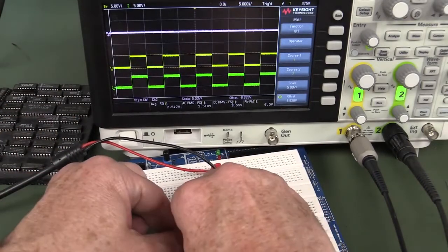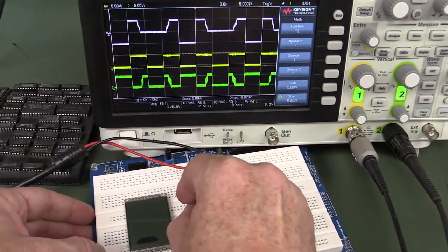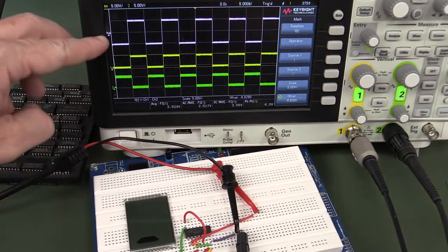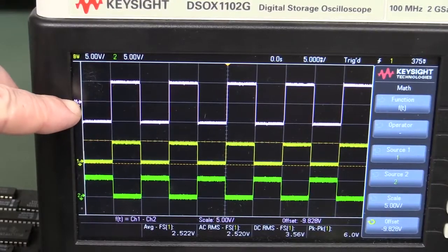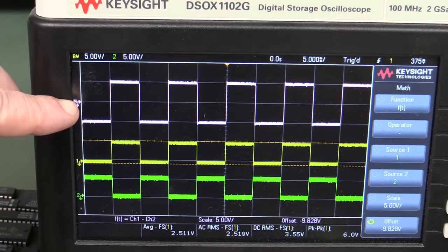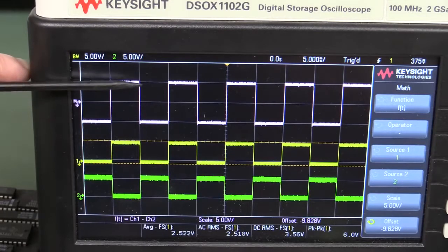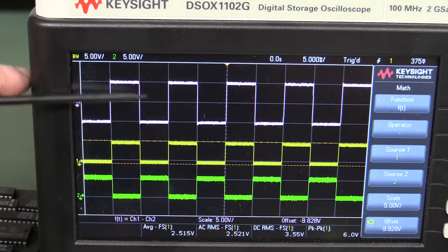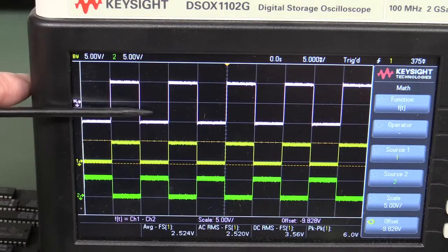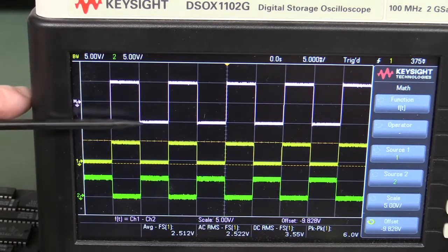But if we strap that pin over to positive there, bingo, the 0 signal, the ground effectively, as far as the LCD is concerned, is smack in the middle there. And it actually goes up by 5 volts and down by 5 volts. So it's actually 10 volts total. So you actually get a greater voltage to drive it.